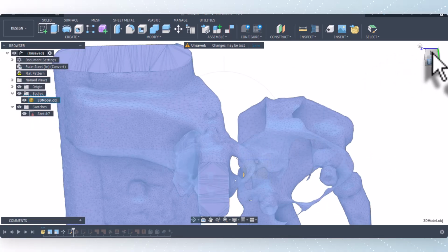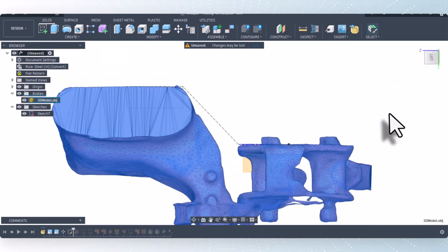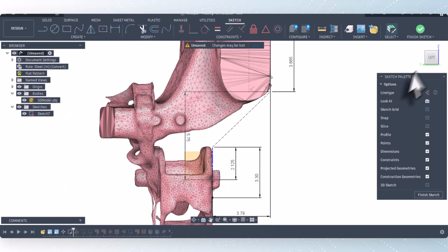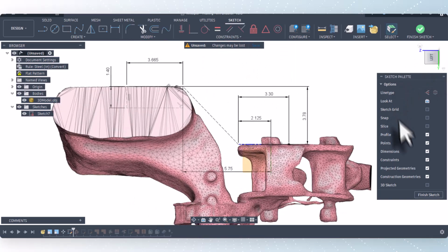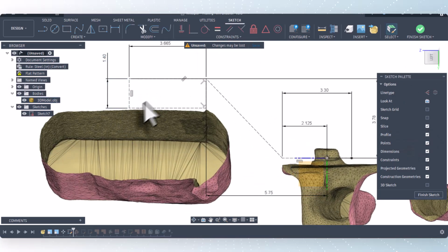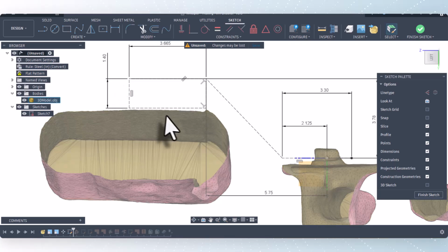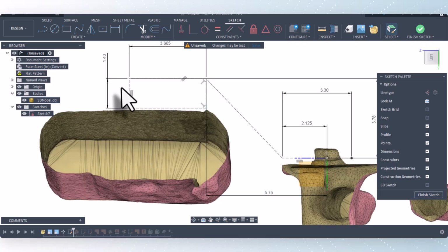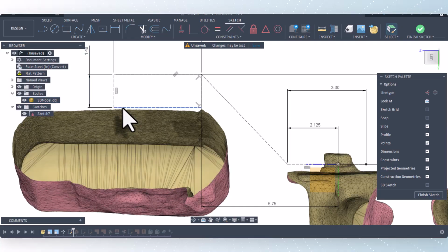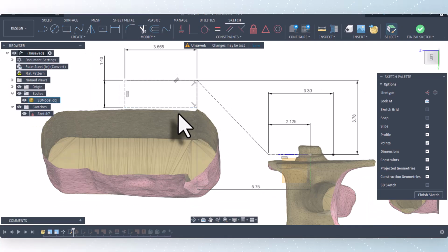And so I'm going to edit that sketch, and let's turn this back around to this orientation. I'm going to go to slice graphics. And so I added this coming down to here, and because this is a mesh and not perfect, I didn't come all the way down to the mesh, leaving myself a little bit of clearance.